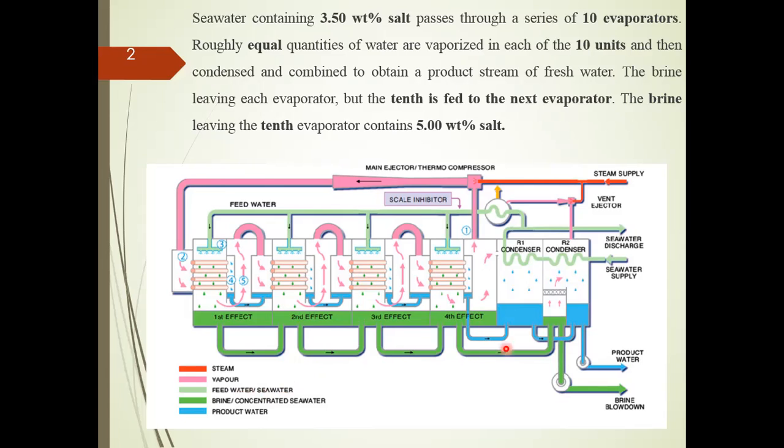And this line is the water feed. This is the feed line, which contains seawater having a lot of salt, which we have to recover in this evaporation process. And at the end, this is our clean water, which we are recovering at the bottom. And this is brine, the solid material recovered at the bottom of the evaporators, and we will continue to treat this brine until it contains minimum moisture, or it becomes 100% dry brine.